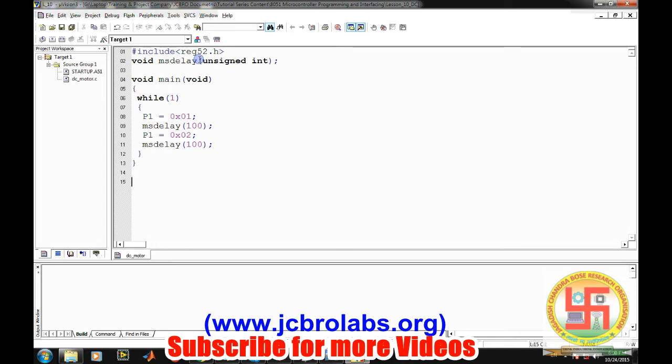Now let's write a delay subroutine, ms delay, unsigned int t, and then unsigned int i, j, and then for i equals 0, i is less than t, and then i plus plus, and then for j equals 0, j is less than 1275, and then j plus plus.